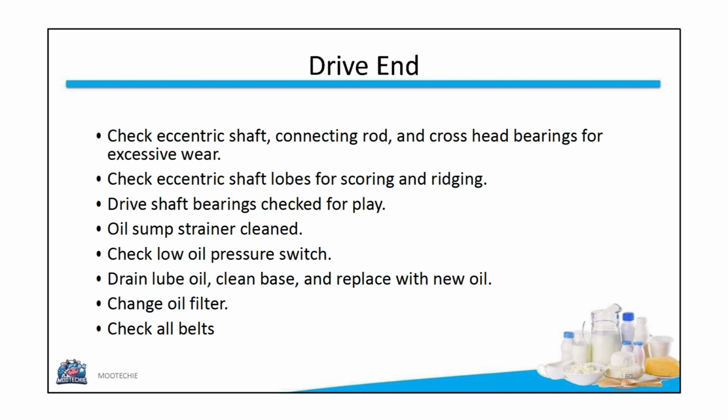Drive shaft bearings must be checked for play. The oil sump strainer should be cleaned. The low oil pressure switch needs to be checked. The lube oil should be drained, the base cleaned, and new oil replaced. The oil filter must be changed, and all belts should be inspected.